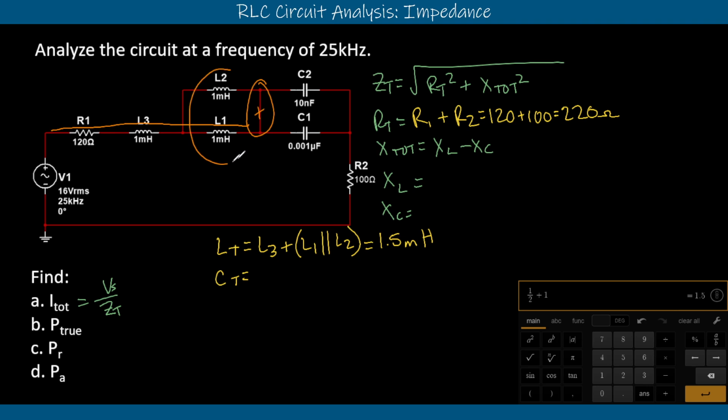Right? So the inductors right here in parallel with each other are in series with the capacitors that are next. Right? And so just don't get fooled by that node. Again, we're only focused on the capacitors, so we're going to go up to this node where they start to split and see that our capacitors go up and down at the same time there. So those two are in parallel.